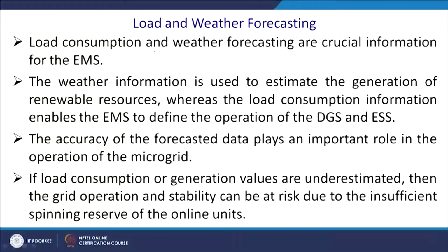Load consumptions and the weather forecastings are crucial for the energy management system. So, you require to know when your peak will occur and how far it is from the input peak of the solar and wind. So, how can we try to match these two peaks by shaping the behavior of the people by the differential tariff, let us say.